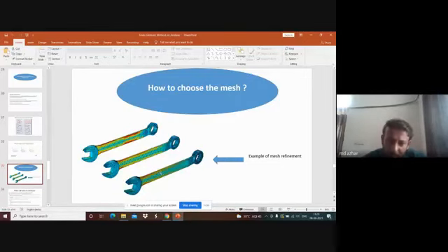Here you can see the highest strains are happening at this particular place, whereas here the strains are high here also. But in this smaller mesh the strains are not low here. So what does it really mean? That your choice of mesh becomes very critical. If you choose the wrong size of mesh, you will have a wrong result.